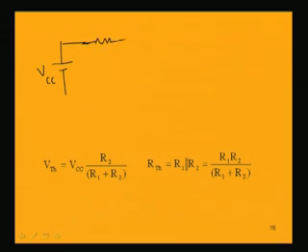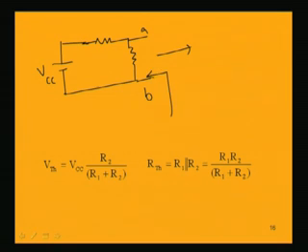Basically, across these 2 points A and B, the right side of this circuit has all those base and collector circuits, but we are finding Thevenin's equivalent looking from this terminal, across AB. So, the Thevenin's equivalent voltage across these 2 points, V Thevenin, can be found out.